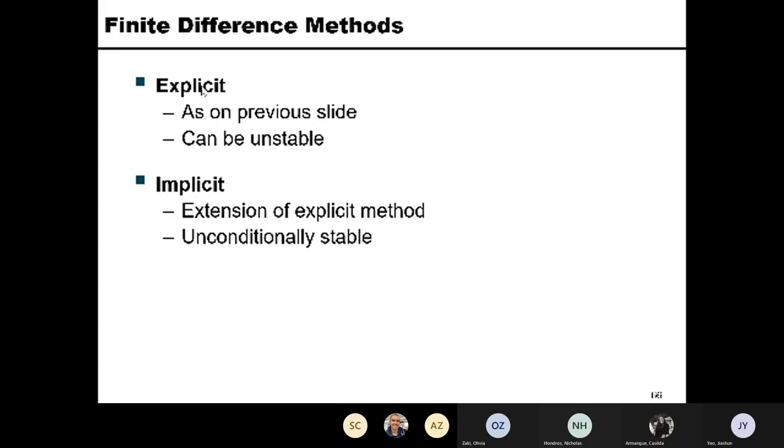First of all, the explicit one accumulates the known results, so any errors in the previous step will be accumulated into the new solution, right? And then numerically it could become unstable, as some errors will be amplified and cause the system to be unstable, all right?